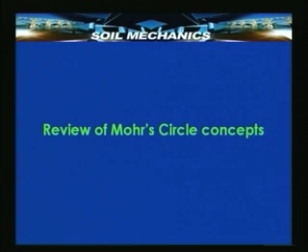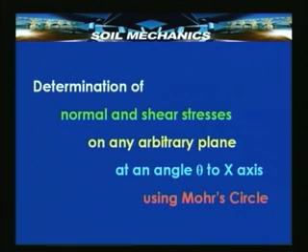So, first a review of the Mohr circle concepts. What is Mohr circle meant for? It is meant for determination of normal and shear stresses on any arbitrary plane at an angle theta to the x axis, and it makes use of the geometrical concept of the circle.